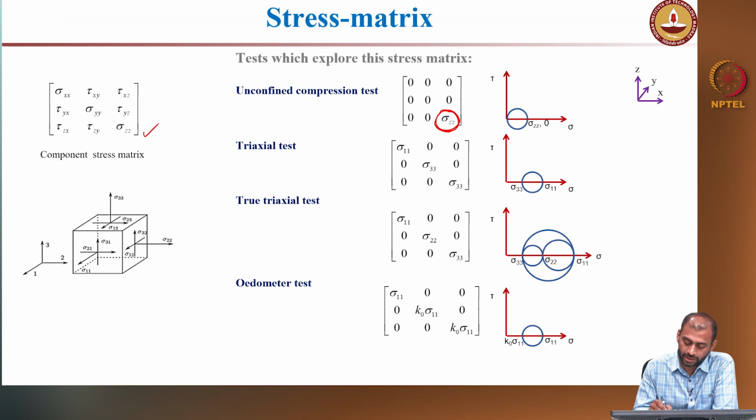When you do a triaxial test, as we discussed earlier, you probe sigma 1 and sigma 3. Also, if you are performing a true triaxial test, you can independently control sigma 1, sigma 2 and sigma 3 and try to understand the material behavior. So you apply true three-dimensional stresses, and then you can vary different stress paths and obtain the response. Right.